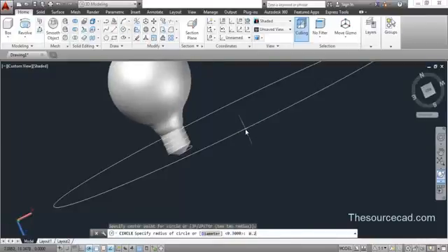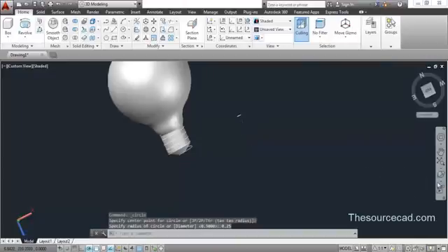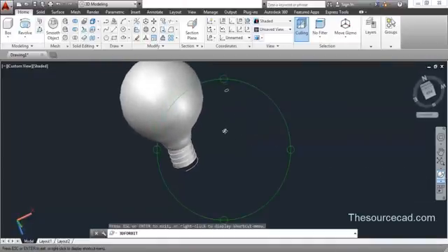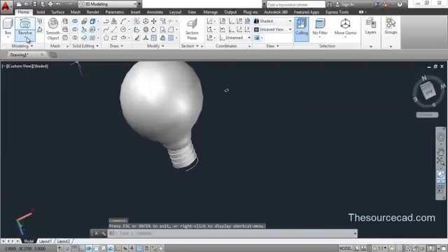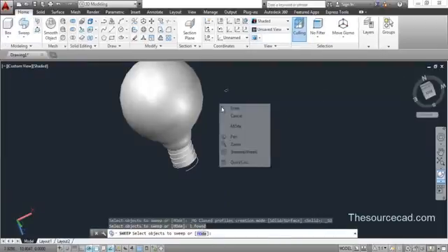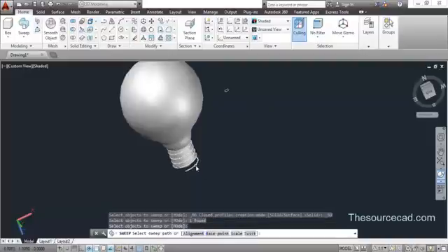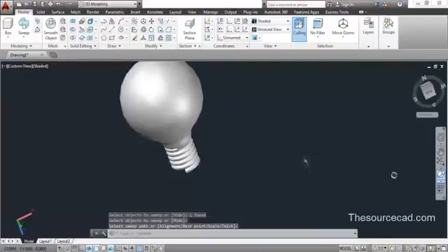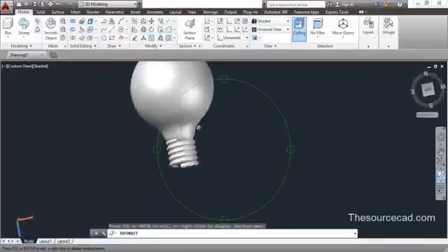Now make a circle again of radius 0.25 units. So here we have the helix and a circle. Now go to the sweep tool, select the circle, press enter and select the helix. Okay, so here you will find this coiled profile after going through all these steps.